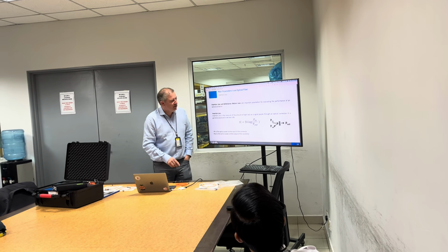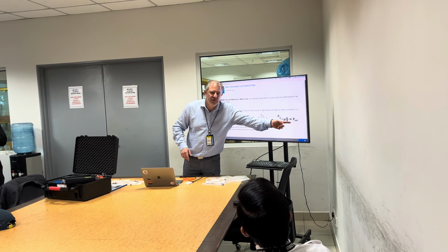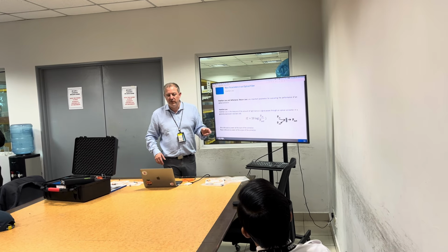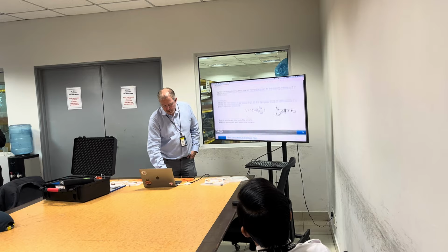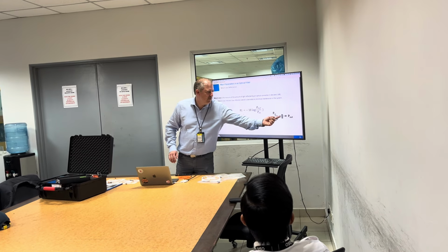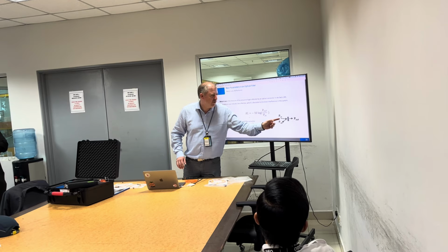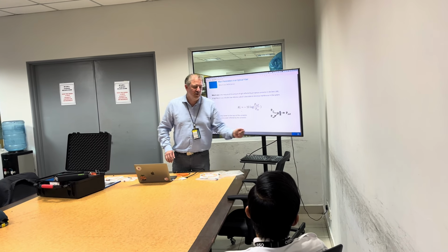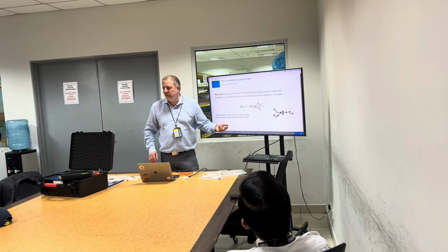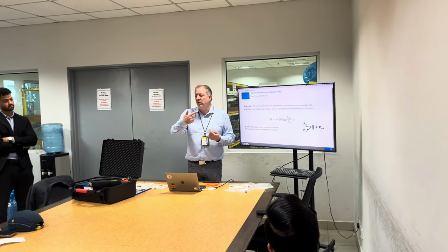So insertion loss, again, is the ratio between the power you put in and the power you have out. And it's 10 log since it's given in dB. Reflectance is the light you got from reflection, so the Pref for reflection, compared to the power you put in. And again, it's minus 10 log, and it's also in dB. So you want the reflectance as low as you can, because you want most of the light to go through the connector.